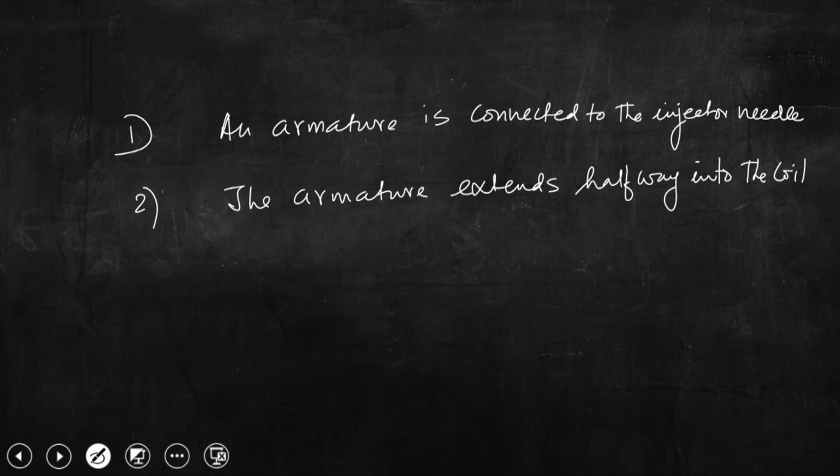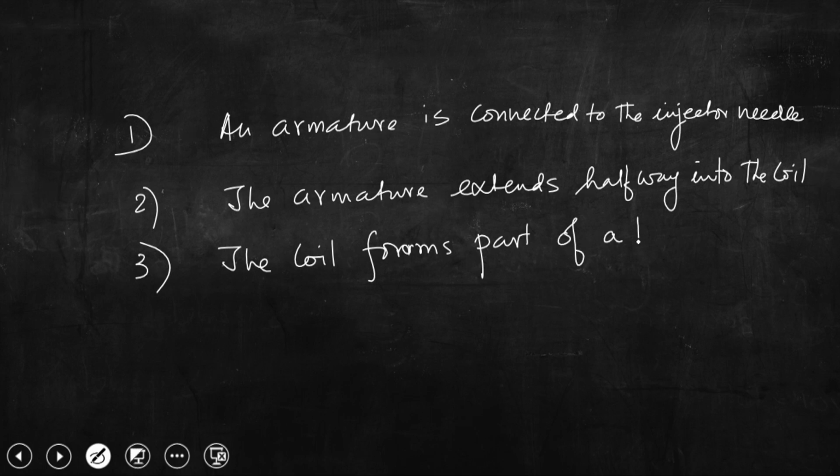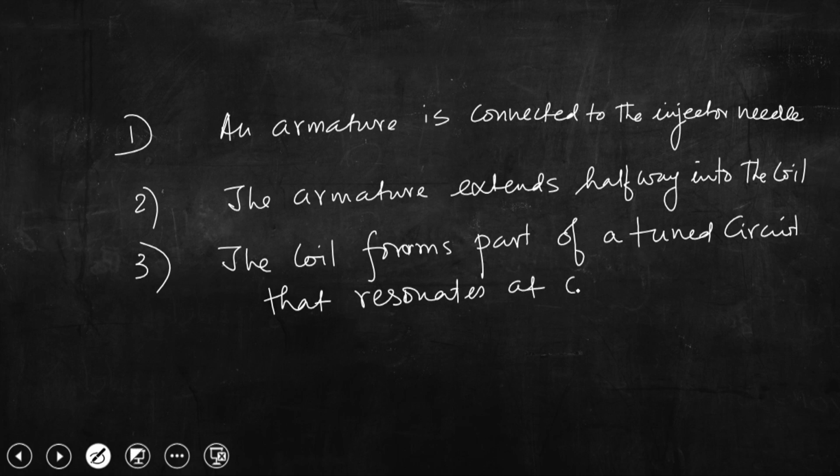So the armature extends halfway into the coil, and number 3, the coil forms part of a tuned circuit that resonates at close to 2 megahertz. Okay.